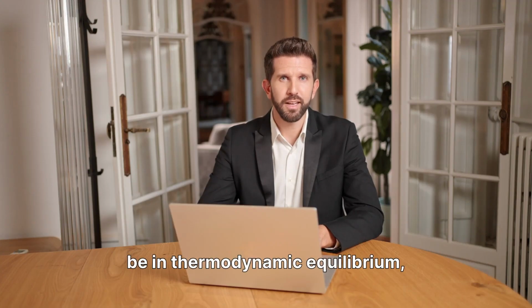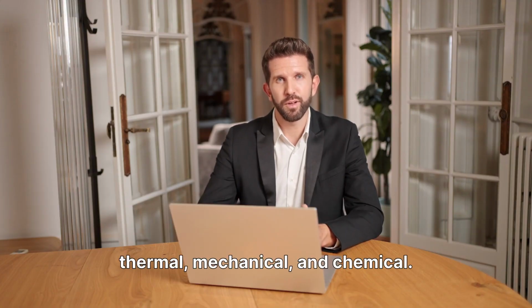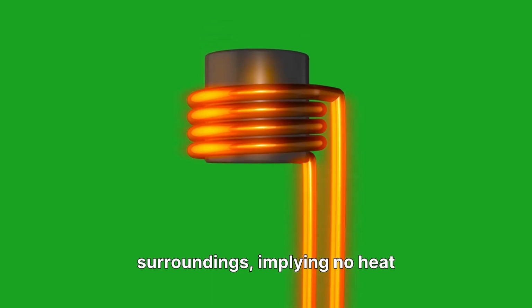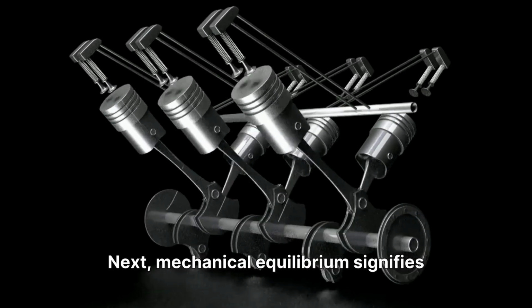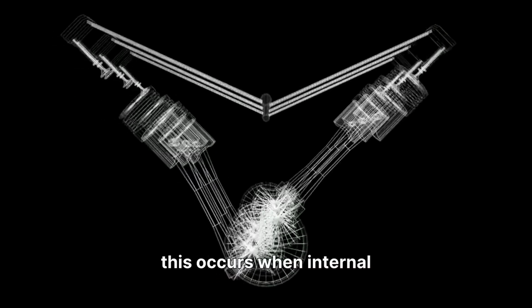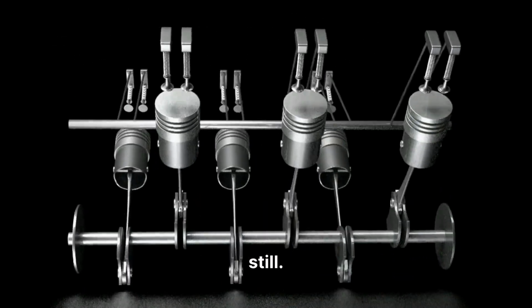For a system to be in thermodynamic equilibrium, three specific types of equilibrium must exist simultaneously: thermal, mechanical, and chemical. First, thermal equilibrium means no temperature difference within the system or between the system and its surroundings, implying no heat transfer. Next, mechanical equilibrium signifies no unbalanced forces or pressure differences. In a piston-cylinder device, this occurs when internal pressure equals external pressure, and the piston remains still.